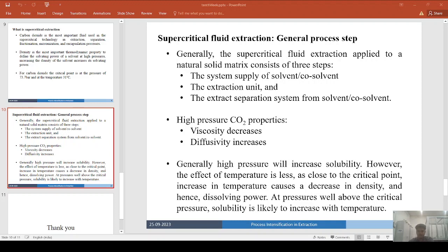To maximize the rate of extraction, the flow rate should be high enough for the extraction to be completely diffusion limited, but that is wasteful of solvent. To minimize the amount of solvent used, the extraction should be completely solubility limited, but then again you would require a long residence time. The flow rate must therefore be determined depending on the competing factors of time, solvent cost, and capital cost of pump, heater and heat exchangers. So the optimum flow rate will probably be somewhere in the region where both solubility and diffusion are significant factors.